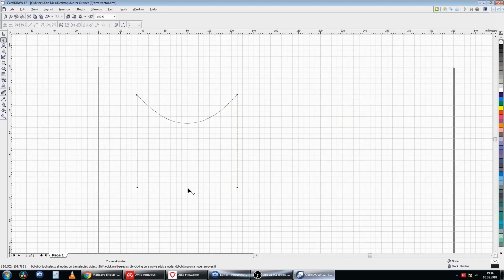Another nice and pretty important thing is when you click, for example, here and you click with your right mouse button again, you have this option breaking apart, which breaks apart the line on the point that you have chosen. So when I drag this up, you see that our line is broken up into 2 segments at the point where I selected it. When I now select one of those little squares and I press delete, those lines will disappear. And sure, I can edit those as well, and I can move them around where I need them and what I want to do. Okay, so this is just the basic of how to edit a shape or how to edit a line.